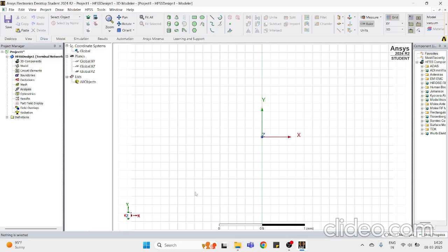And then you'll be checking these S parameters and electric fields. So the S parameters will help you determine how much power is being transmitted through the microstrip line and how much is getting reflected. Ideally, everything should get transmitted since it's a microstrip line. But yeah, you'll see that there will be some reflections, and unless the reflections are under a certain value, it will not be a concern for us. So we'll just have to make sure that some of these parameters are in line with what we are doing.